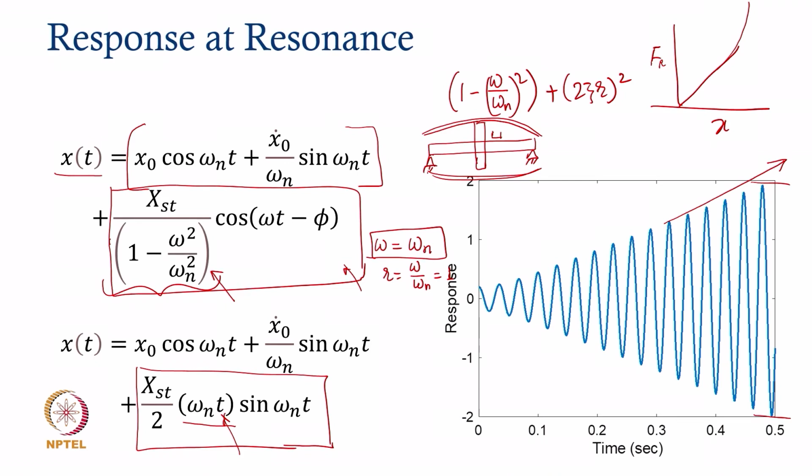There will be some rubbing, there will be impacting conditions, and the amplitude will not practically go to an infinite value. However, it is also important to understand that large amplitudes are going to create secondary problems or failures of such high speed rotors.